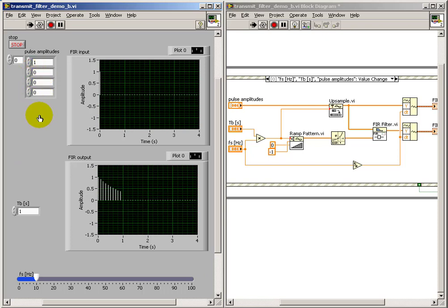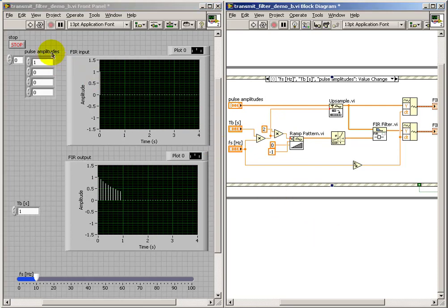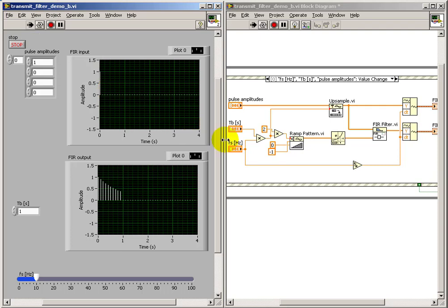All right, let me revert back to just a single impulse at the beginning, but I want to keep the number of bit intervals spread out to 4. Now supposing I do a little bit of a manipulation here such that the exponential exists over multiple bit periods. In this case, the exponential exists over 2 bit periods. And this actually happens all the time with communication systems, where you might have your prototype pulse extending over many bit periods, as it turns out.